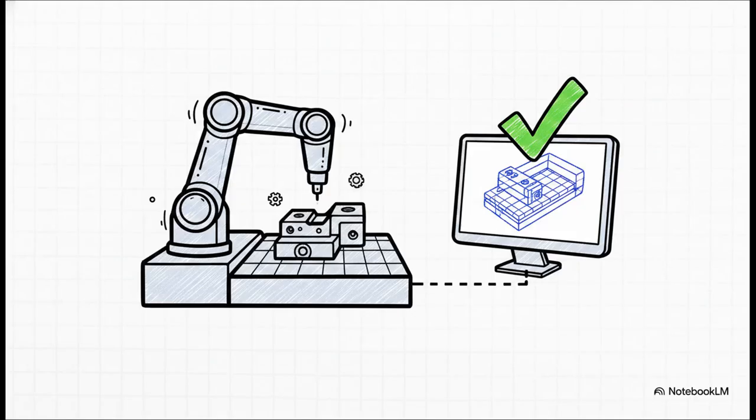And on the digital side, things are even cooler. Modern manufacturing relies heavily on CMMs, or coordinate measuring machines. When a designer uses semantic GD&T, meaning the feature control frames are built with actual data intelligence right inside the 3D CAD model, the CMM software can import those rules directly. The software literally guides the operator to align the datums, completely eliminates manual math errors, and spits out an automated pass-fail report based exactly on what that feature control frame dictated. It's incredibly fast and insanely accurate.